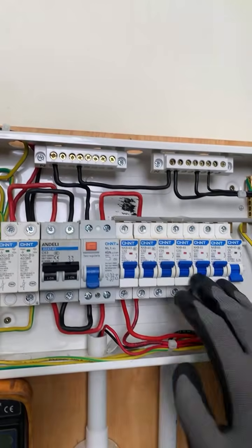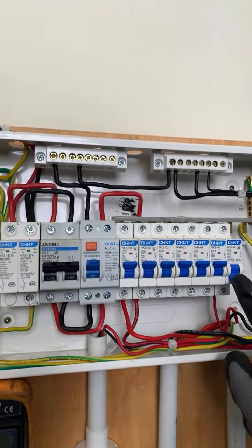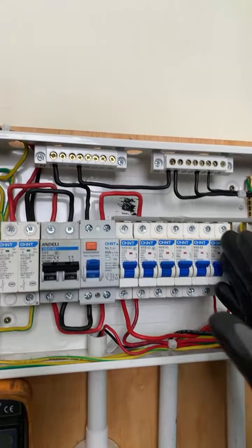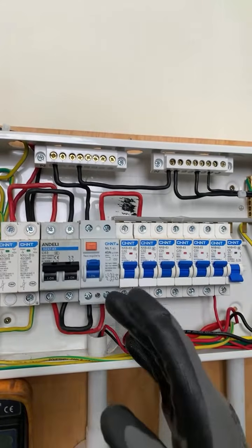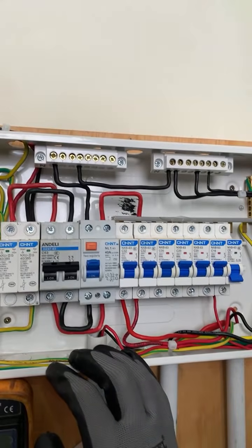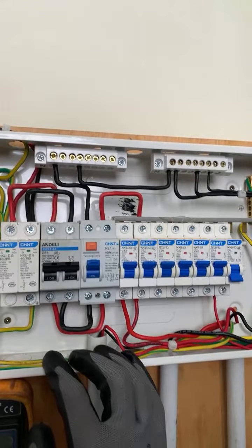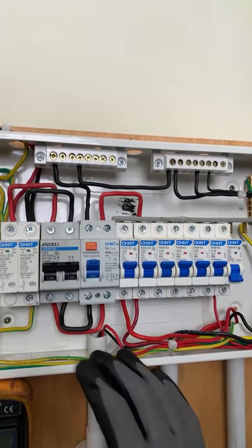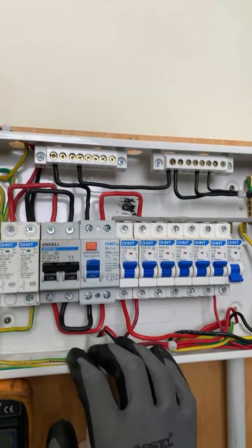So assuming the customer has called you and this MCB here has tripped, there is a problem. It simply means that, for instance, the example we were giving, there is no power in the kitchen, no lighting in the dining area, and also the balcony or probably the corridor. Then it definitely cannot be that the bulbs in those sections blew up.